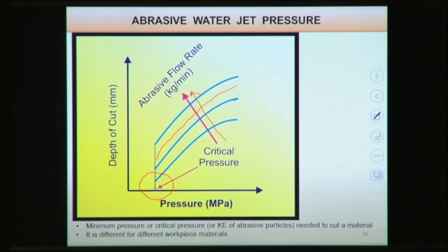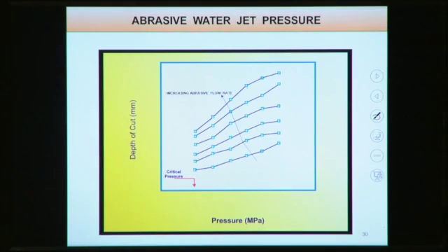Okay, so it is different for different workpiece materials. So this critical pressure is different for different workpiece materials. Again, we can see here that with increasing pressure, depth of cut also increases. Increasing the abrasive flow rate also increases the depth of cut.